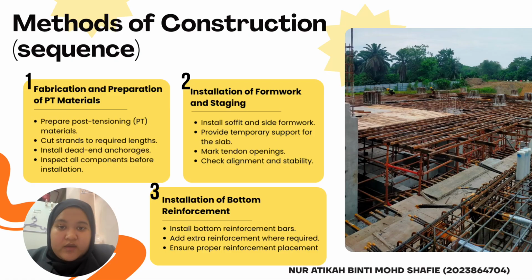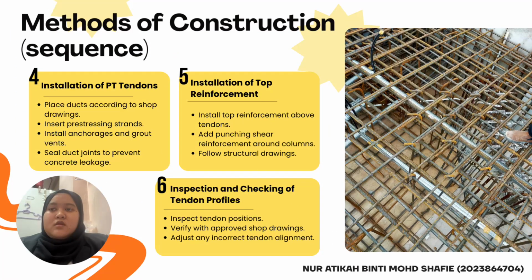For number 3, we have installation of bottom reinforcement. We must install bottom reinforcement bars. Add extra reinforcement where required. Ensure proper reinforcement placement. For number 4, we have installation of PT materials. We have to place them according to shop drawings. Insert prestressing strands. Install anchorage and grout vents. Seal duct joints to prevent concrete leaking.